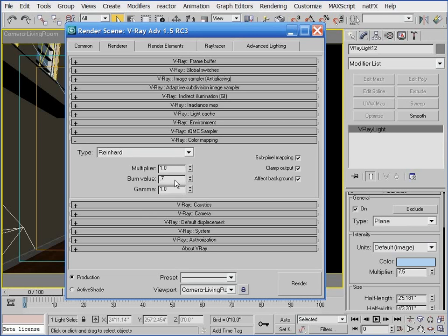So once I switch to exponential and set the bright and dark multipliers back to 1.0, their default values, I know my scene is going to render with a little more darker look than it previously did when I used less exponential color mapping. What I want to try here is a bright and dark multiplier value of 2.0. Basically double the apparent illumination of my scene.